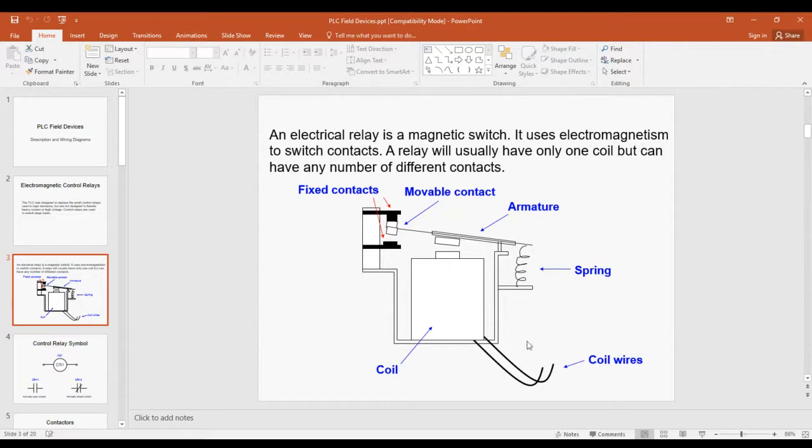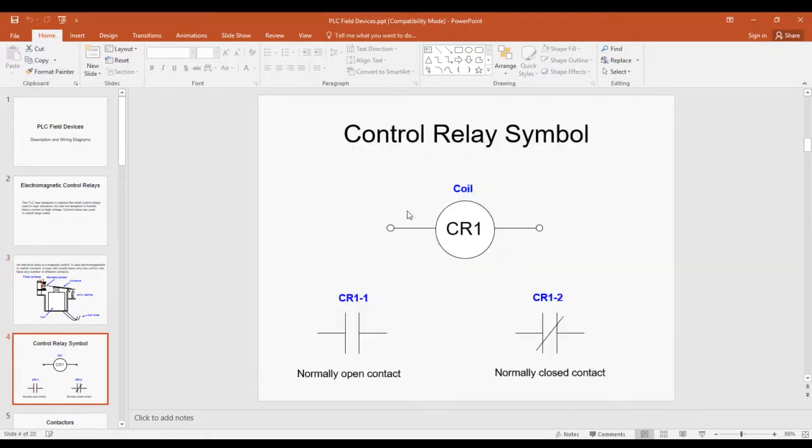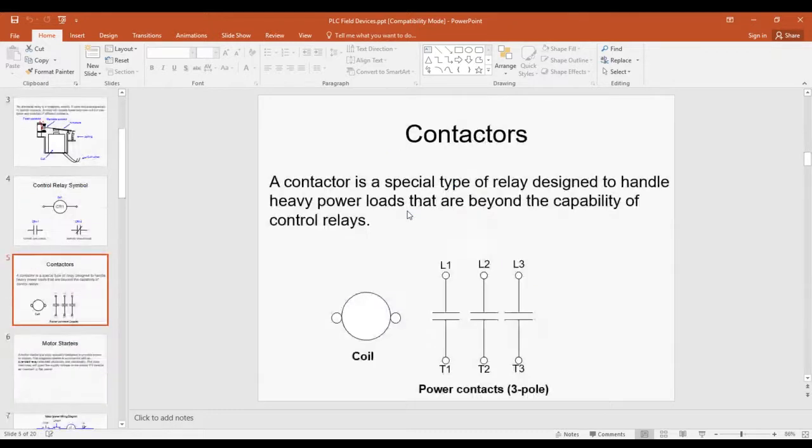The part you control with your key switch would be the coil circuit. You stick your key in, you turn a low current switch, and so you're controlling current to basically a coil that electromagnetically moves the armature down to actually engage the starter motor. So there's an example where you're using a low current circuit, i.e. your ignition circuit or switch, to control a large current, your starter motor in your car. That's a good example. So you've seen these symbols before in your relay ladder logic.